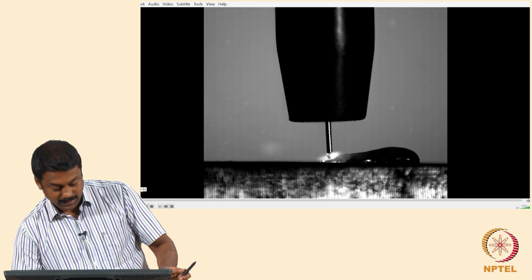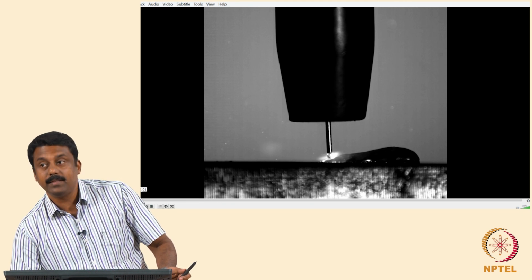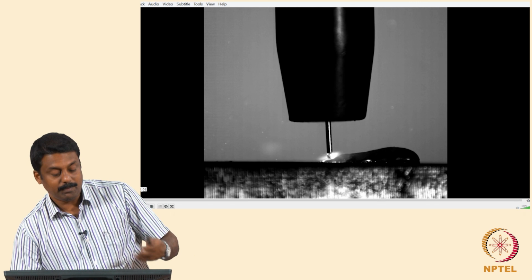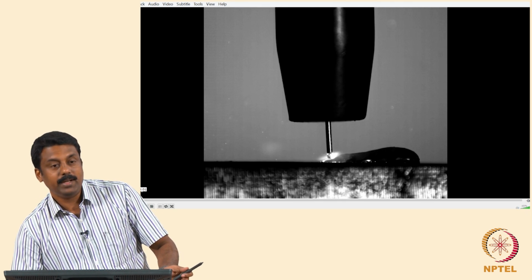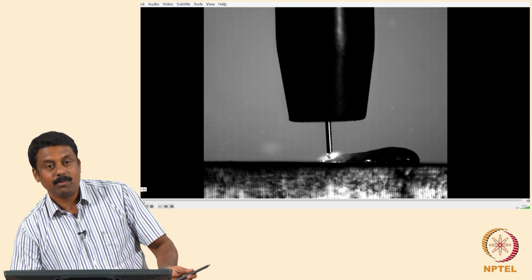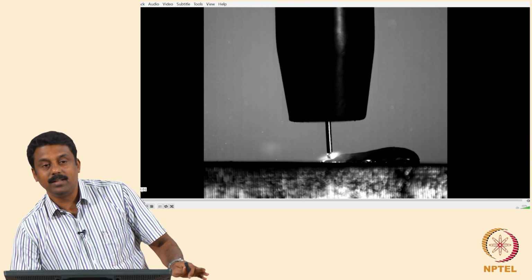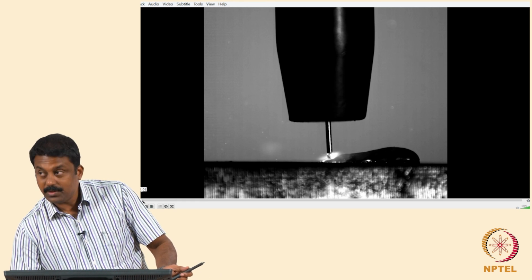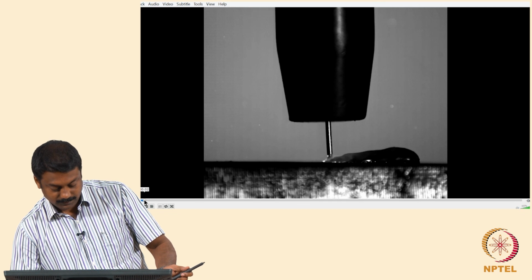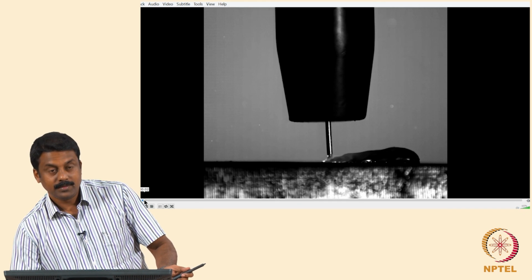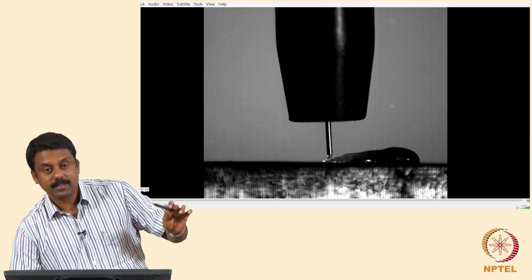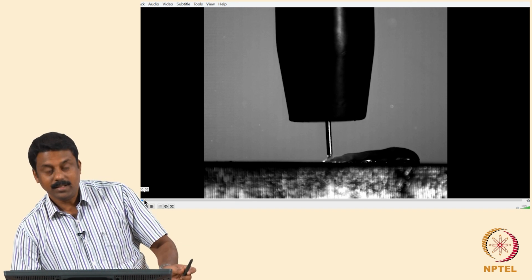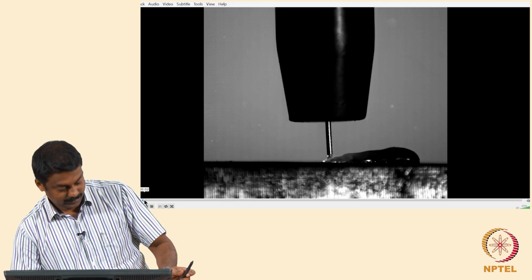Okay. And then the moment the short circuiting event happens, the power source switches off the current. Okay. So then the power source can detect the short circuiting event by measuring the voltage. The moment the voltage becomes extremely small, that means that short circuiting has happened. Okay. And then the current is switched off, the arc is completely gone. So now the wire can be retracted back, and during this process the surface tension of the pool pulls the droplet with its surface. Okay.